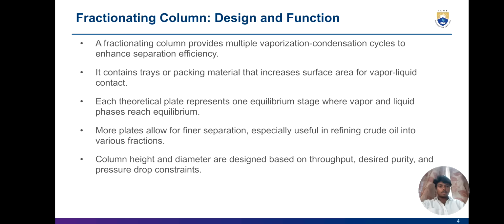Fractionating column design and function. A fractionating column provides multiple vaporization-condensation cycles to enhance separation efficiency. It contains trays or packing material that increases surface area for vapor-liquid contact. Each theoretical plate represents one equilibrium stage where vapor and liquid phases reach equilibrium. More plates allow for finer separation, especially useful in refining crude oil into various fractions. Column height and diameter are designed based on throughput, desired purity, and pressure drop constraints.